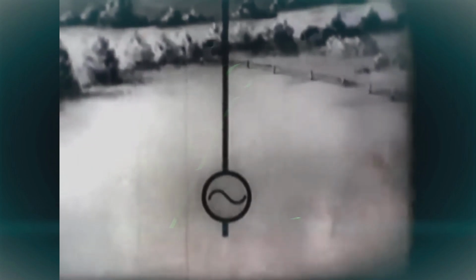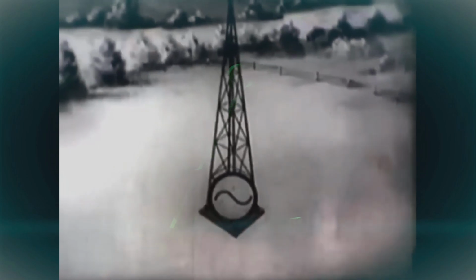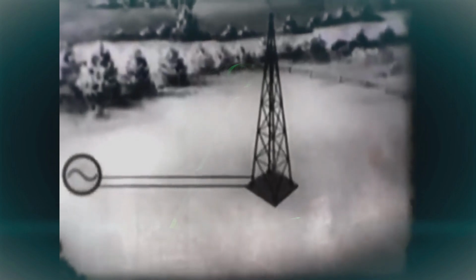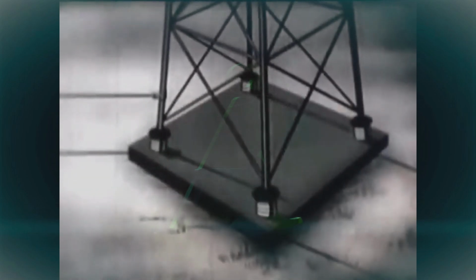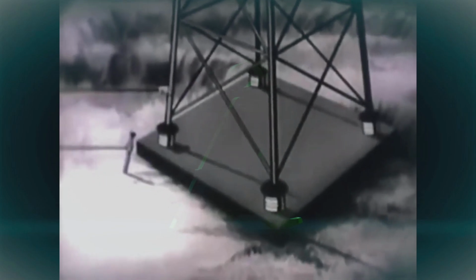The ground takes the place of the lower conductor. The upright conductor becomes an antenna tower. Our source of power becomes a transmitter, which is located some distance from the tower to prevent distortion of radiation patterns. The efficiency of a quarter-wave antenna depends largely on the nature of the ground. At installations near the sea or in salt marshland, the Earth's conductivity is excellent, and a simple metal stake provides proper ground.